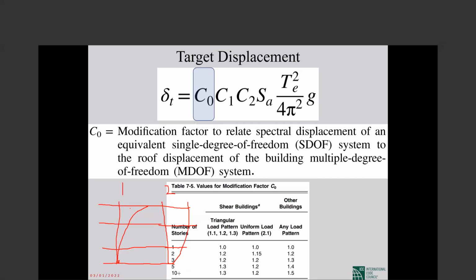A frame, you can neglect the shear deformation in beams and columns of that. But the general form of the frame behavior for a multi-bay, multi-story frame is like type 2. So it's shear type deformation, but you neglect the shear deformation in elements.